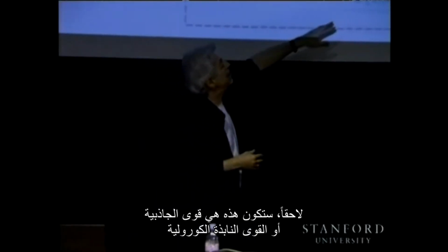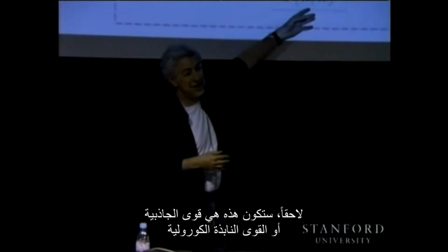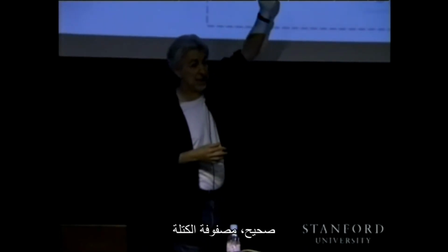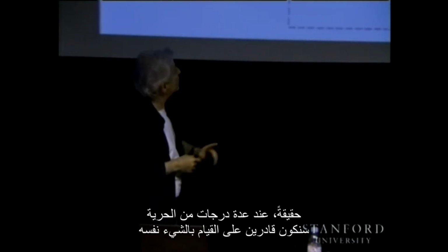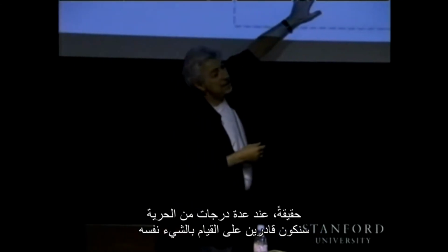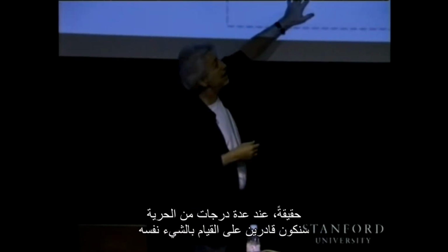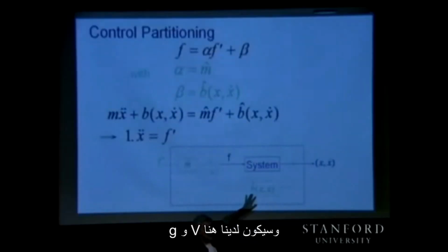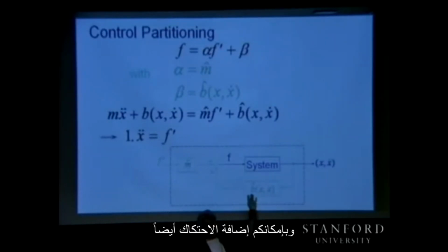Later, this will be centrifugal Coriolis gravity forces, and this would be what? Right, the mass matrix. So in fact, with many degrees of freedom, we will be able to do the same thing, where this becomes the mass matrix, and here we will have V and G. You remember V? Centrifugal Coriolis, and G, gravity, and you can add the friction as well.